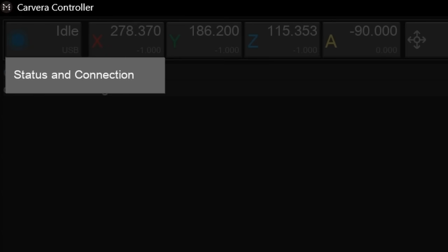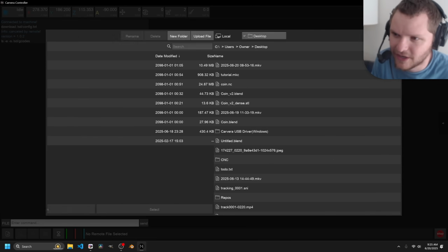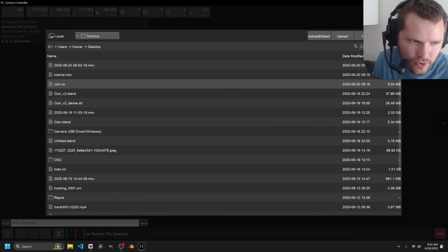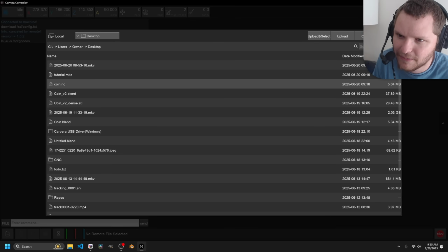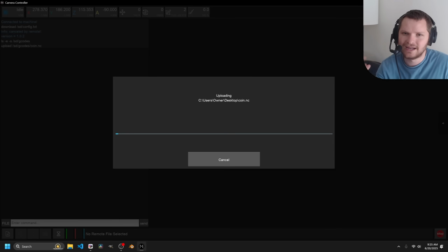Okay, there we go. You want to see this blue idle. And now let's bring in the G code and hope for the best. So to do this, you want to upload a file, find the one you made. So that's coin.nc, which is 5 megabytes, hit upload and select. And do expect this to take a moment, longer than you think,